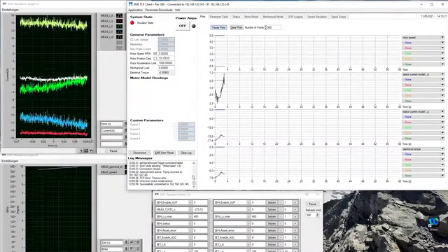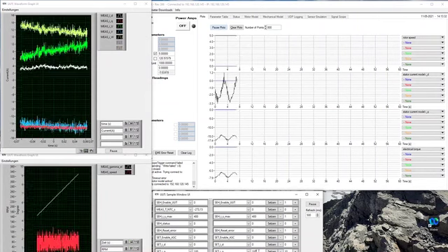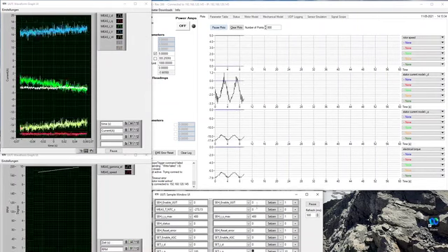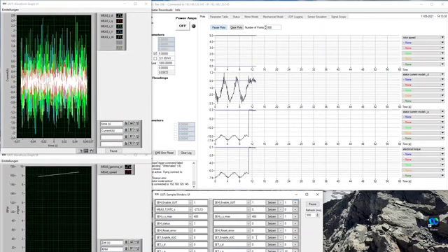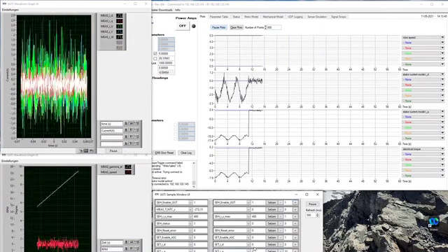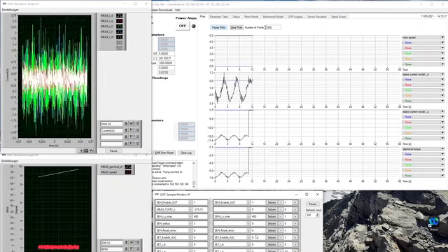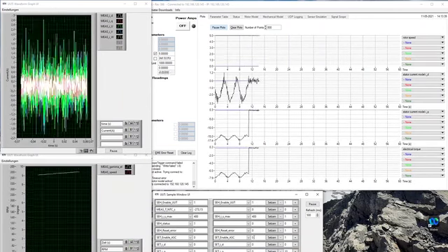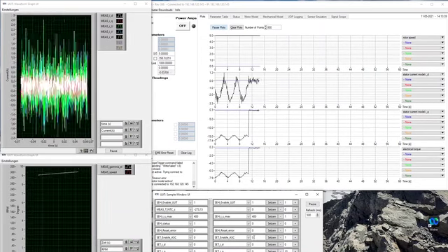Firstly, we would like to show the inverter operation in current control mode. The inverter is set to current control mode. The initial rotor speed is set to 5 RPM. The initial current set points are 0. Then the UUT is enabled. The actual D and Q currents vary around their 0 set points.